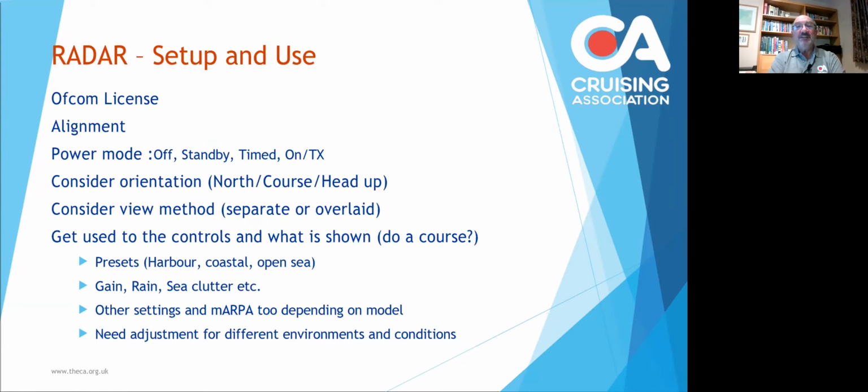Head up is probably the least useful, particularly on a small boat, because with head up, the boat turning slightly will mean that the radar image is constantly rotating a little bit one way and then a little bit the other way. So my suggestion would be north or course up.